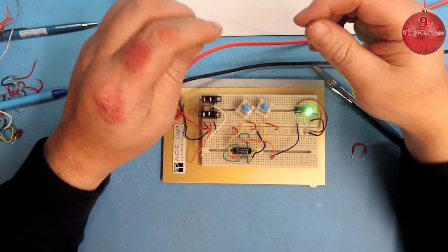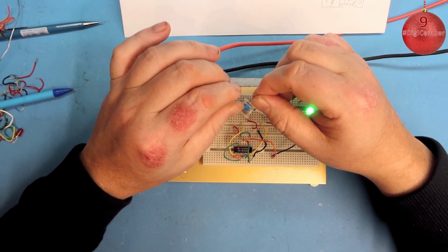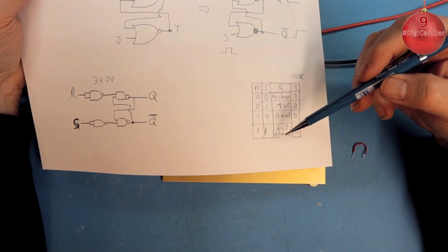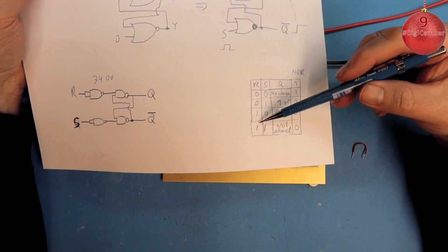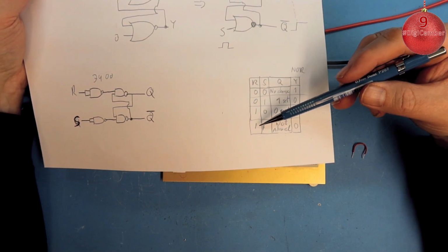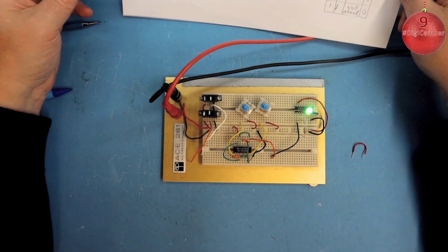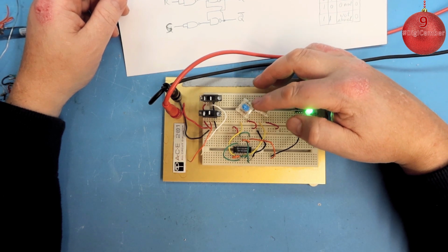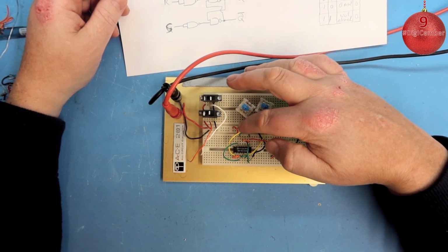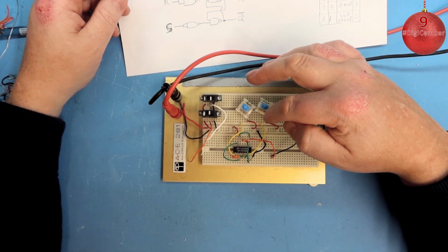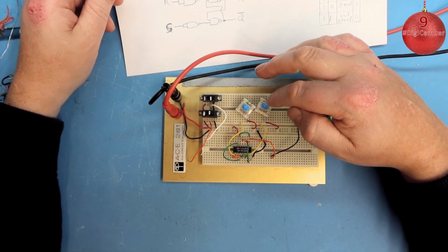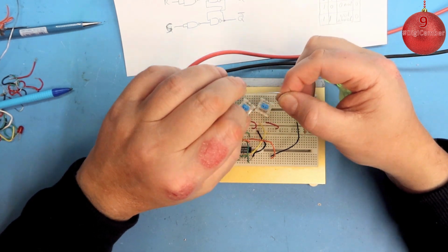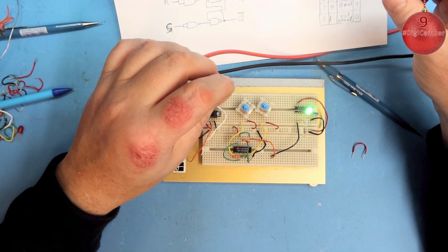Yes, and what I've actually done wrong or forgot is that in this truth table here you actually have one illegal situation, and that is not allowed: 1 and 1 on the RS. And what is happening here? Yes, I have hooked this to high, but what happens when these are not high? They are dangling. So this output here is actually not connected to ground. So what I need to do is have this connected to ground.